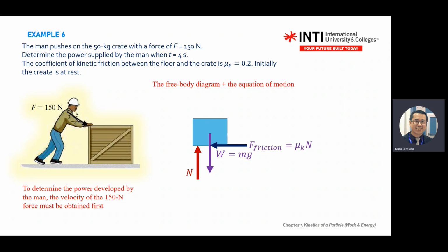What else is missing in a free body diagram? The force. So include the force. How do you draw the force? Normally, I will recommend the force goes through the center of the object. So from chapter 3 onwards, I highly recommend to focus all the force through the center of mass or center of gravity. Well, you can draw some axis from the center, and then all the force will go through there.